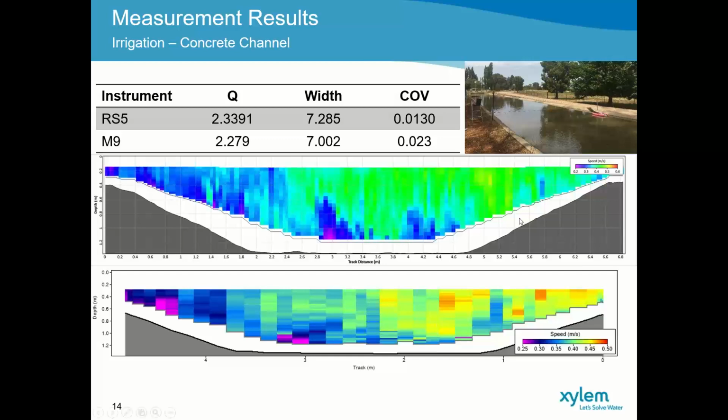I'm not sure if you can notice there, but this tagline design was set up by Murrumbidgee Irrigation. It's shaped in a triangle, and it allows the operator to stand next to the post and move the instrument instead of bending over to reposition the instrument. There's also a flexible mat, if you can see there, that's connected between the board and the tagline, and that reduces lateral movement and improves accuracy of the measurement.